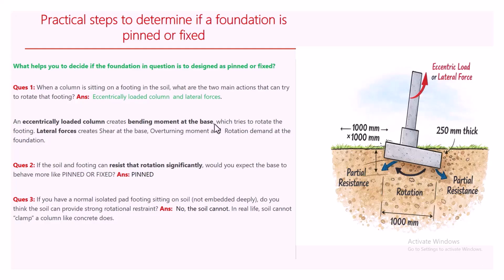Then the lateral forces create shear at the base, overturning moment and rotation, and rotation demand on the foundation. So these are the effects. This now describes this picture. So this is how it behaves when there is an eccentric load or a lateral force.